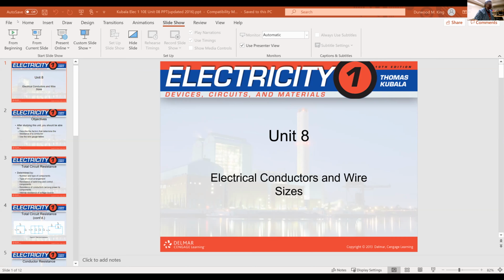When you start getting in that kind of length, the resistance of the wires matter. You start getting something called voltage drop, and that matters. You got to calculate all that in. So this chapter and Chapter 9 are going to help you to get a full understanding, so that if you had a hog house way off the highway, and you knew the total amp load of that building, you can actually put the footage into this formula, the footage in, the amps you got to have, and all of that, and that formula will tell you the wire size you got to have to keep from having too much voltage drop. So that formula comes in Chapter 9. That this chapter gets you ready for.